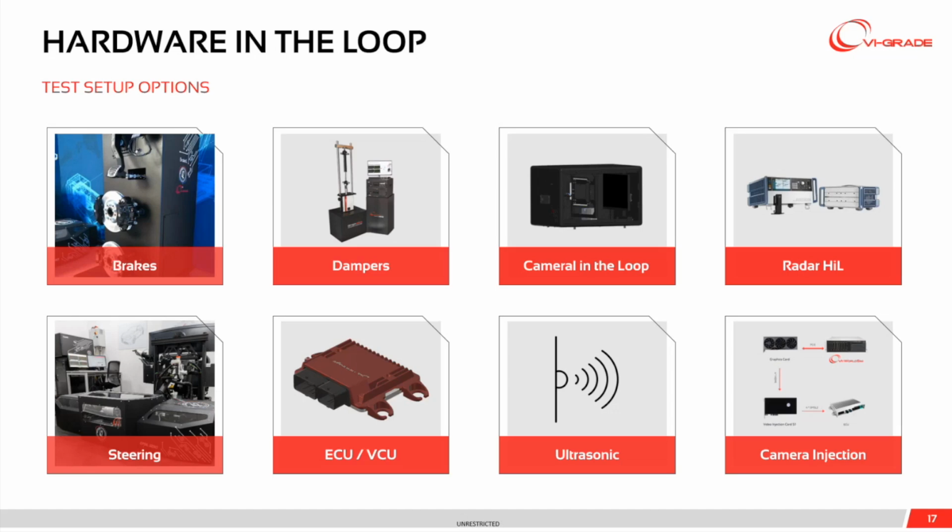As you're evaluating cameras, we can actually point cameras at a WorldSim screen and have that camera perceive and operate as if it was looking at a real world, although it's really just looking at a screen. We can do ultrasonic simulation, hardware in the loop, where we actually have physical ultrasonic sensors within the loop, providing that information back to the simulation.